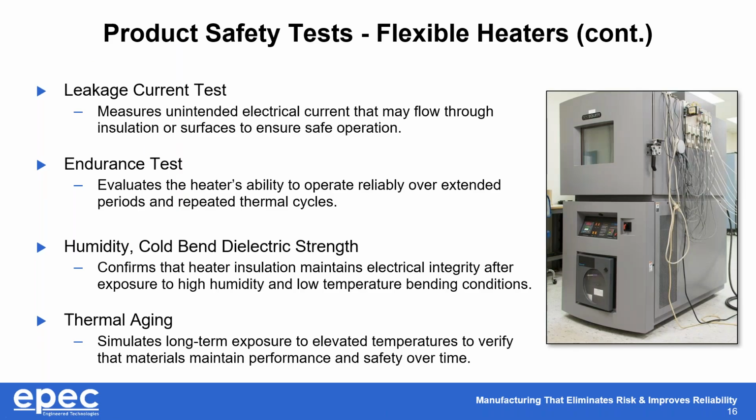Other electrical tests include a leakage current test, which helps detect an inadvertent flow of current outside the heater, which then could be a safety hazard or otherwise damage equipment. Endurance tests are performed to verify that the heater will perform reliably over long periods of time. This can take several weeks and involves various temperature cycling and energizing the heater. The heater must operate throughout the entire time.